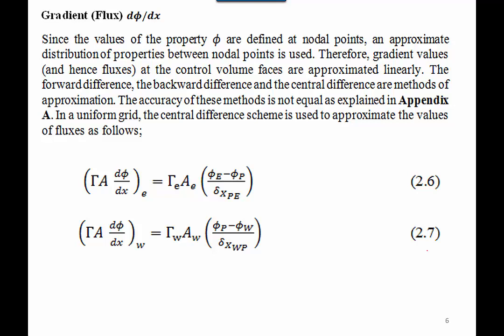Therefore, gradient values and hence fluxes at the control volume faces are approximated linearly. That means we will use a linear approximation, which is either forward difference, backward difference or central difference. These three approximation methods are adopted, and the accuracy of these methods will differ from one to another.